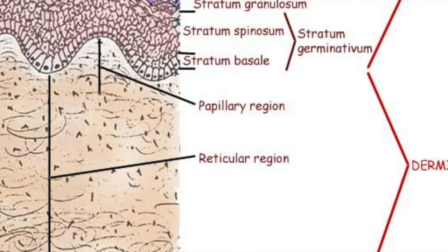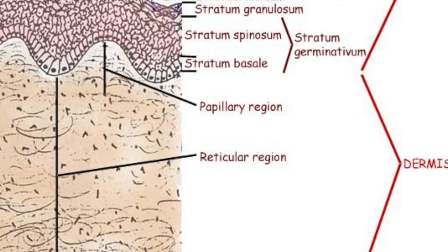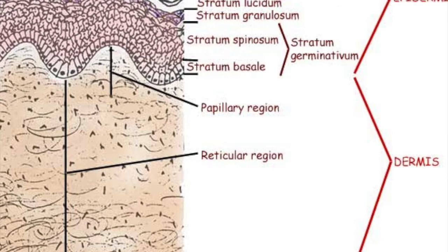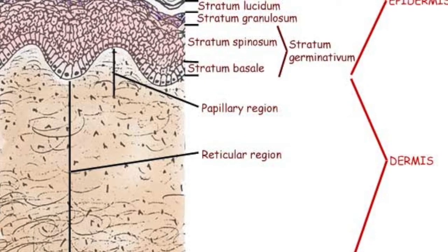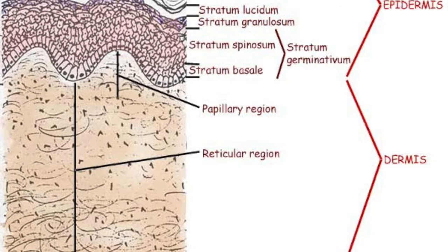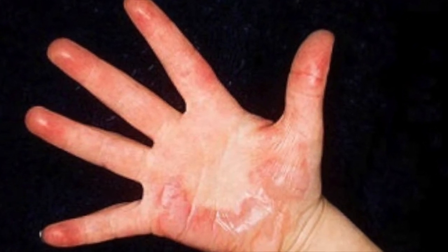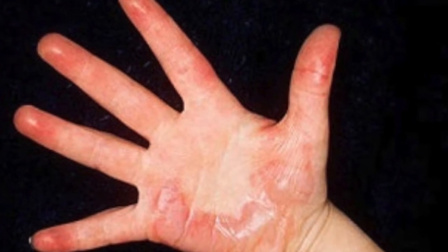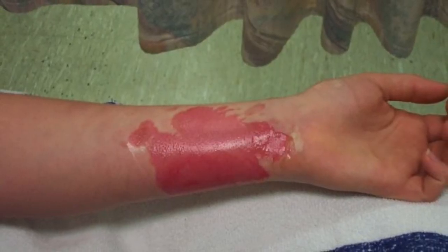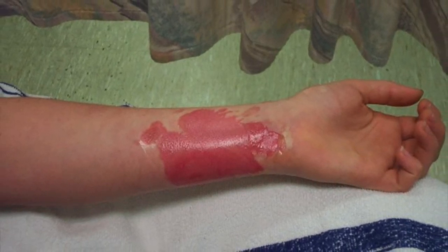The flow of current through a resistive material is always associated with the production of heat. The primary resistive material of the human body is the epidermis, the layer of dead skin cells that lies on top of the dermis. This layer of skin is relatively dry, and the cells themselves are also dry, having died and released their moisture. Thus, this layer of skin provides a reasonable amount of resistance to the flow of electricity. Once electricity enters the body through the skin, it encounters very little resistance due to the electrolytes, conductive fluids, contained within the body. Therefore, the skin is where the greatest heating occurs, since the heat is proportional to the resistance.